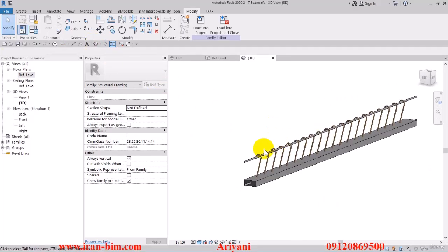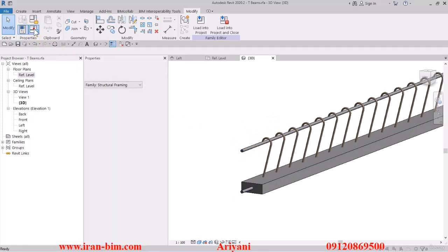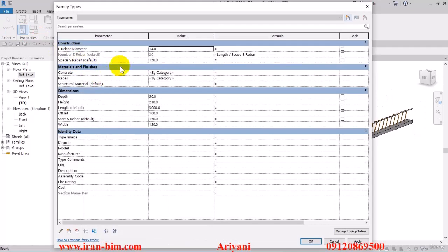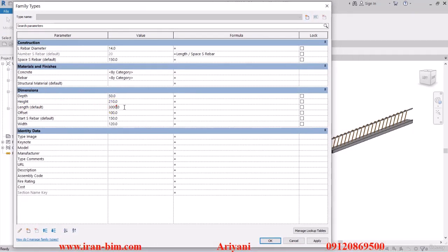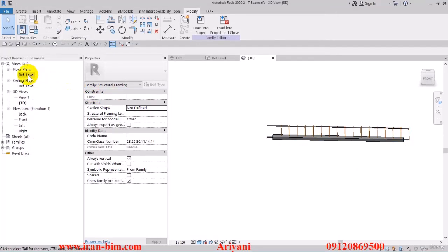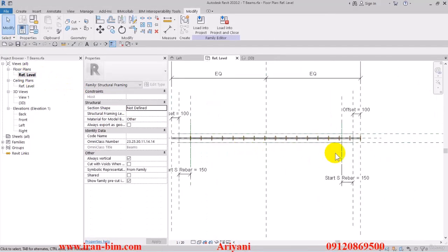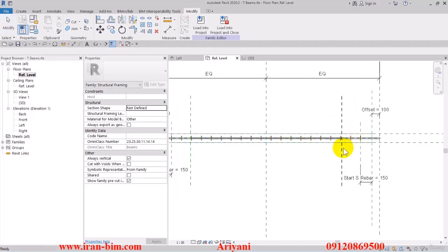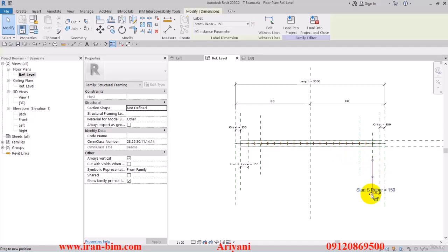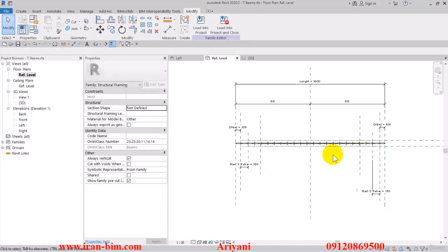All right, let me just open up the family types again. Looks fine, close it. So I'll go back here and change the length to 2500 here, apply, then OK. And now this part has been messed up. It's not a big problem, we'll fix it. So here, Control Z. Let me just pull this down here. So the rest of them look fine for now.